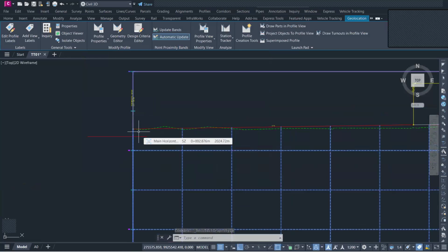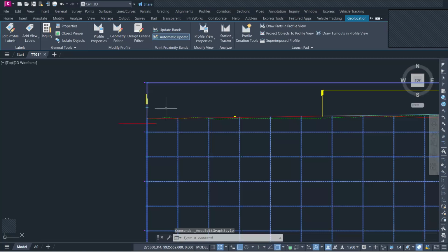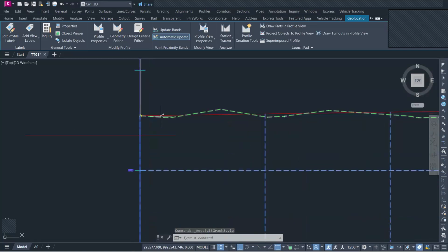This is super easy. So we'll say if our subgrade is 300, it means that is 0.3 meters. And then we are going to multiply it by the vertical exaggeration. So you will come again to profile view and you will multiply this times 2 so that you can get 0.6. So what this means is instead of 0.3, or lowering our vertical profile by 0.3, we lower it by 0.6.